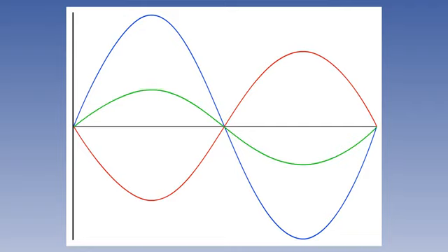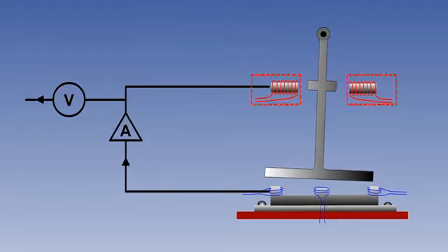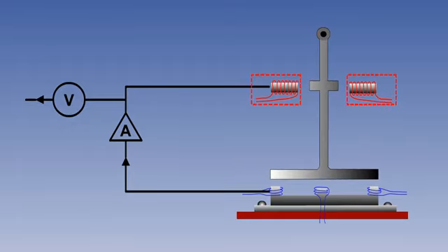This secondary induced voltage is passed to a feedback amplifier, where it is amplified, phase detected and rectified to DC. The DC is then passed to solenoids, which act as electromagnets, and attract a permanent magnet in such a sense as to recentralize it. A voltage is picked off and measured downstream of the amplifier. This voltage will be proportional to the restoring force, and therefore the initial acceleration. By measuring the amplifier output voltage, we have a measure of lateral acceleration.